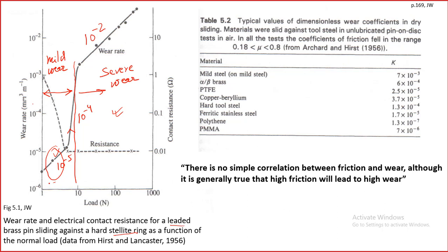So that's why we need this kind of data, so that we can design and select the material very suitably, so that the load is within the mild wear regime. It should never be in the severe wear regime, because this is almost like a failure.